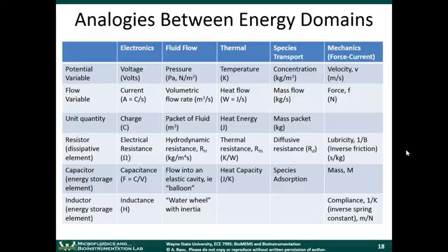Now, in mechanics, the energy storage element is mass, because when a mass is moving at a specific velocity, it has inertia. It has kinetic energy. All right, it has momentum. That momentum itself is a form of energy storage. That's why this can be represented as a capacitor.